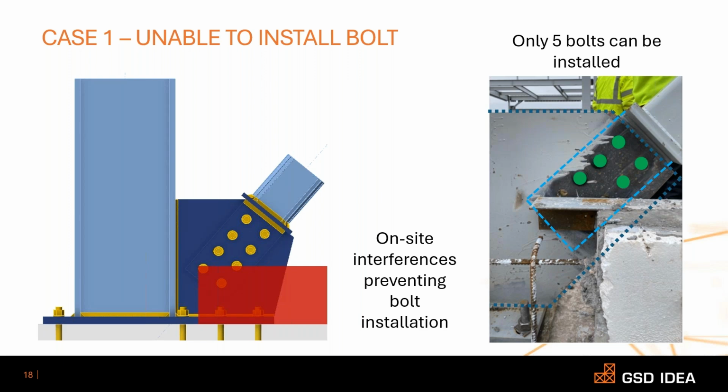We also need to consider the eccentric loading since the bolts are not symmetrical. As you can see, the CG of the bolt group will lie away from the member CG, so the eccentric moments will be generated, which we have to consider in the re-evaluation of this connection design. If you are using a manual template, like MathCAD or an Excel sheet, we have to spend a lot of time modifying the template to accommodate all these considerations.